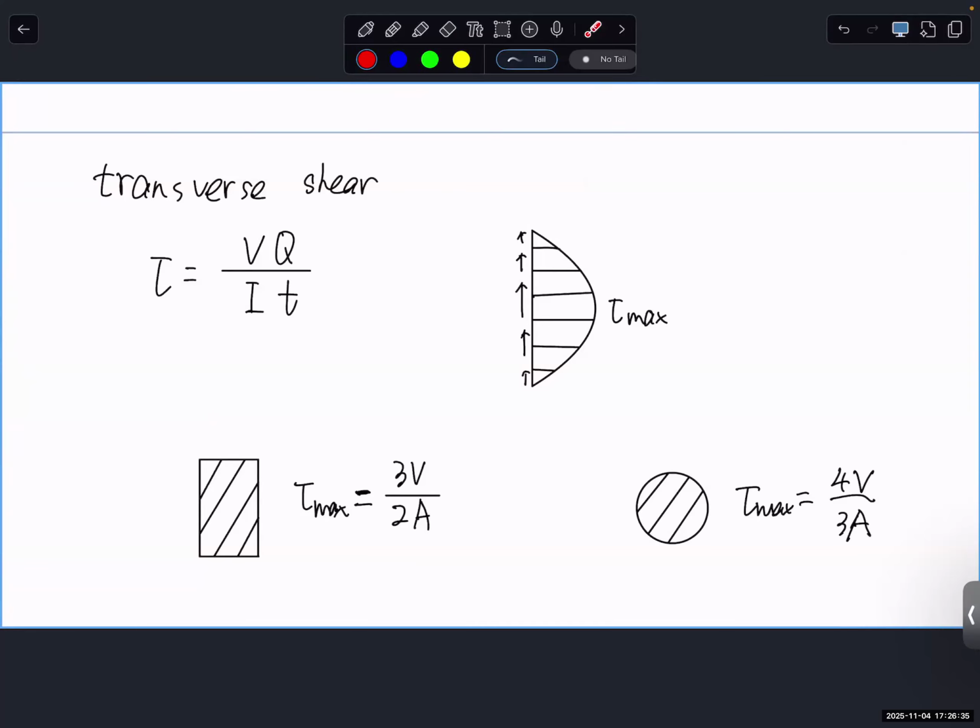So this dimension times force equals the maximum bending moment, and maximum stress should be on this cross section, at the top and the bottom, of course: maximum compressive, maximum tensile. The transverse shear is basically when you apply force in this way, it also generates transverse shear at the same time. So I still use this one as example.